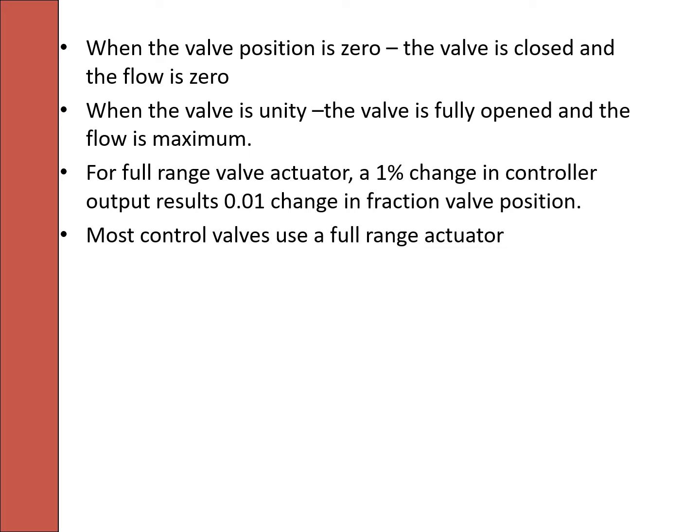So for a full range valve actuator, a 1% change in the controller output results in a 0.01 change in the fraction of valve position. The most common control valve is a full range actuator.